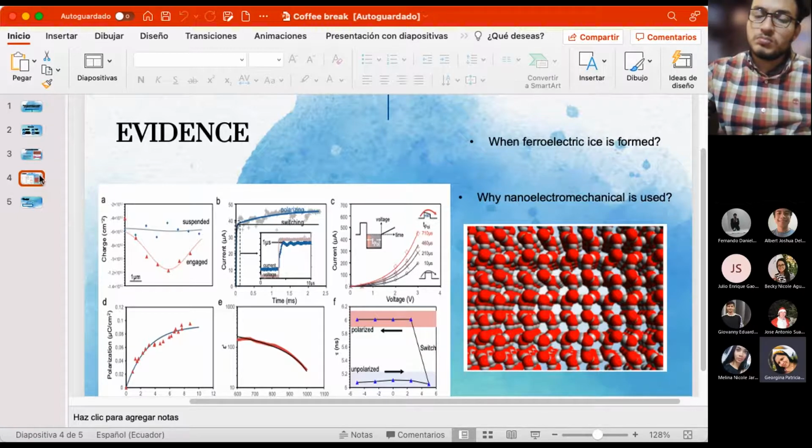In picture 2A, you can see the result of the Raman analysis. Raman is a spectroscopy study. This analysis reveals a doubling of the p-type doping in the center of the suspended area and provides the first evidence for the ferroelectric nature of the process.